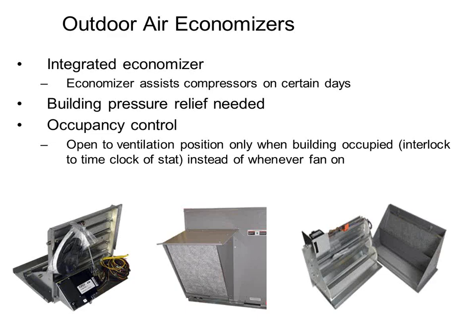Building pressure control means I would want a variable speed exhaust fan, and I would measure the pressure in the building. For most building types, I'd try to maintain some slightly positive pressure, right? So a little bit of air leaks out of the building instead of a little bit of air leaking in. The better of the two evils. And I'll typically try to maintain between 0.03 and 0.08 inches of water column, and I'll ramp up my modulating exhaust fan based on that.